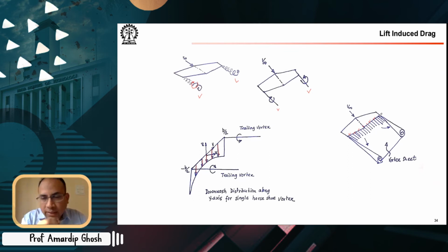In fact, there are some very interesting visualization studies of vortex rings generated by a vortex generator, and there you have multiple vortices that are being shed, and you can see how the trajectories of different vortex rings are being influenced by one another. Okay, so the contrails throughout the span induce or influence the velocity of each other, and eventually they roll up into this kind of vortex sheet. So the two ways of looking at it are kind of similar. Only in Prandtl's, the near field effect is properly modeled. In Lanchester's, the far field effect is properly modeled.